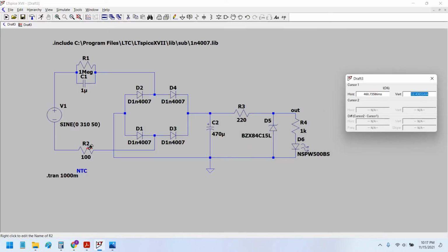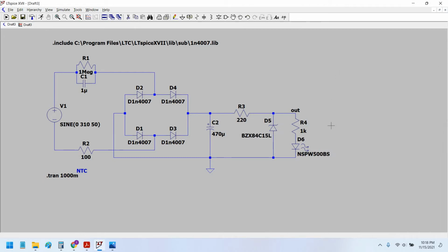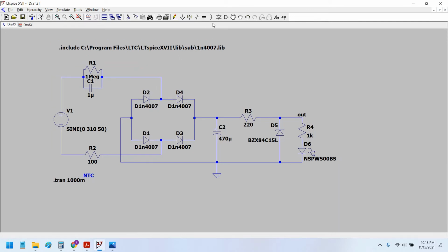This is because of this resistor, because we have used such a high resistance value in order to protect our circuit, this LED, from being damaged. We use this resistance to protect against surge current, inrush current during the capacitor charge up. So there is a remedy for this. The solution for this is to use a transistor, a shunt transistor.